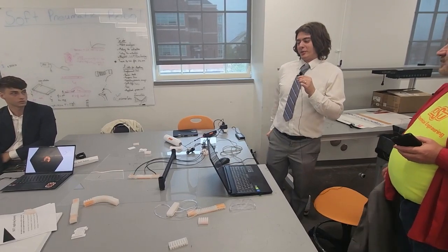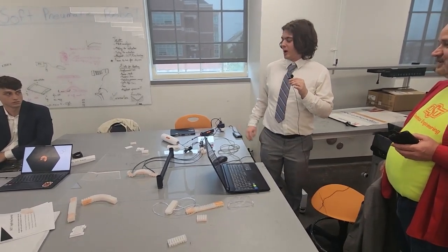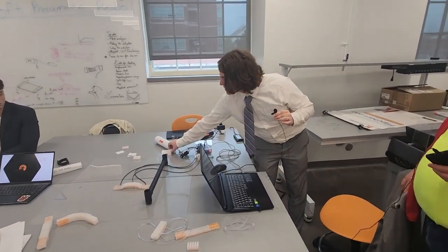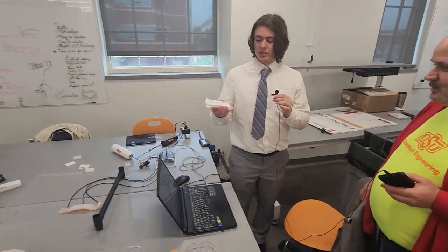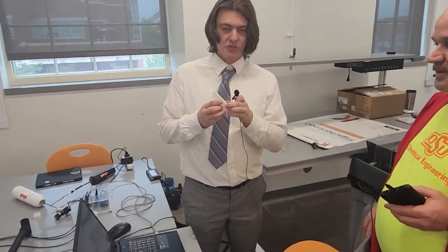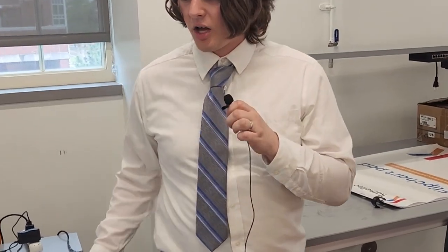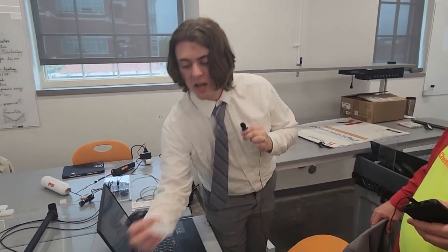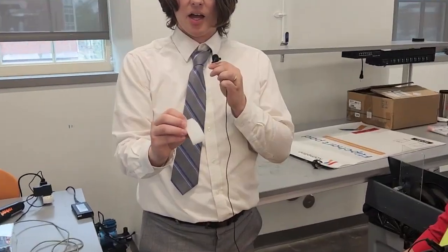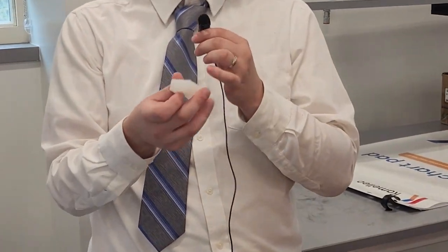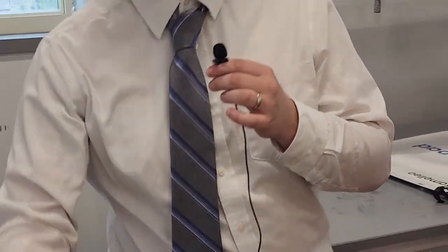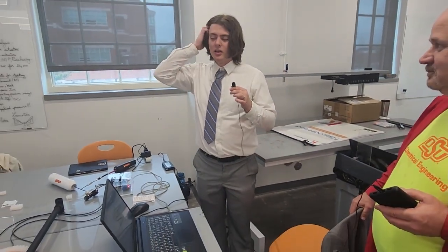Yeah, manufacturing was real fun for this one. All of this manufacturing is accomplished through pouring silicone into 3D printed molds. These molds are two parts that allow for us to develop actuators with air chambers and a fill line that allows us to expand and contract whenever there's an applied pressure.